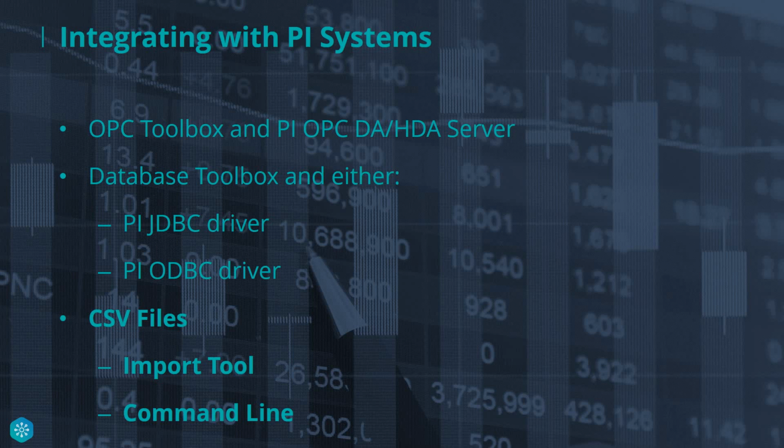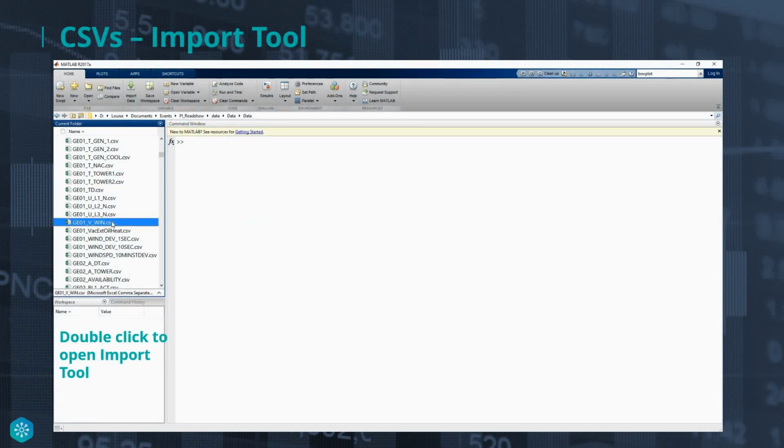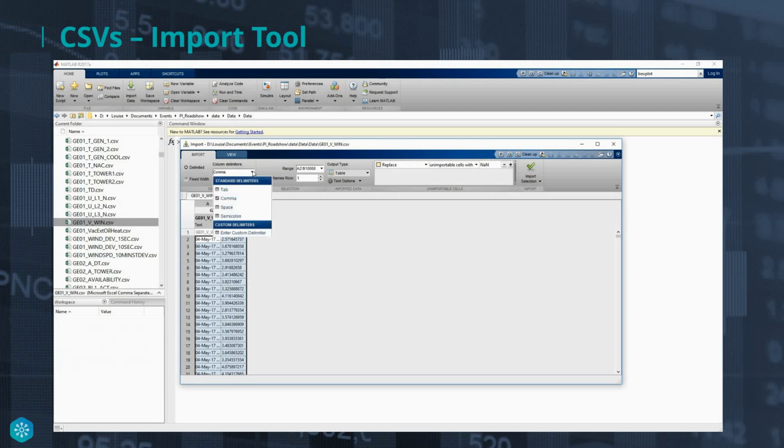If we have a look at our final way of integrating with the PI systems, that being with CSV files, we can either import this using the import tool or a command line interface. The import tool can be opened by double-clicking on a CSV file. From here, you'll be able to set the delimiter type, the range, the output type of the data, as well as what will happen to missing data.